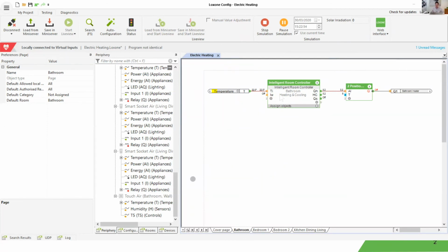And there you go. This has already started working. So now we're at 22 degrees. You can see it's outputting a value of 3.2, which is too low for this to turn back on because this has to hit 7 again. So if I started dropping the temperature down, so the room was cooling down, and again, gave that a little bit of time to work out its internal logic and what's happening with that, we should see this figure rising.